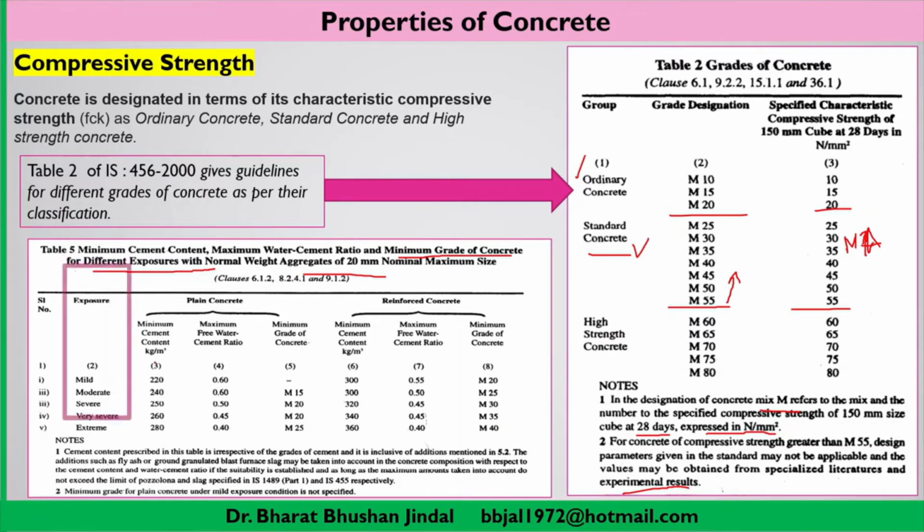So you can see here in the first column some exposure conditions which are mentioned as per IS 456, that is mild condition, moderate condition, severe, very severe and extreme. And correspondingly, as we are more interested in reinforced concrete, because most of the design detailing will be for reinforced cement concrete, the code has very clearly mentioned what should be the minimum grade of concrete.